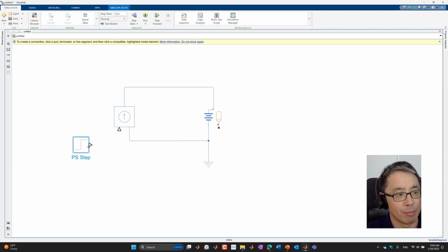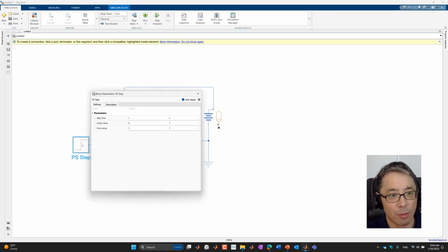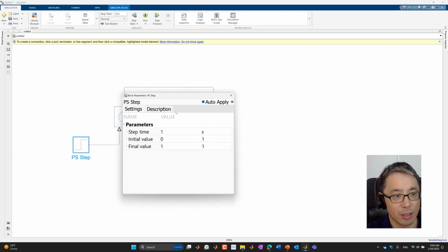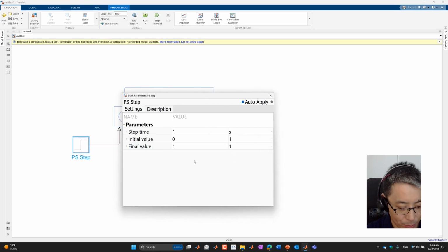And then I'm using this physical signal generator. I can define a physical signal specifying how much current I want to run through the controlled current source, and when I want to turn the current on and off. So I'm going to make the font size here bigger so it's more legible. The way to do it is just to press Control and plus on your keyboard if you are practicing this along with me.